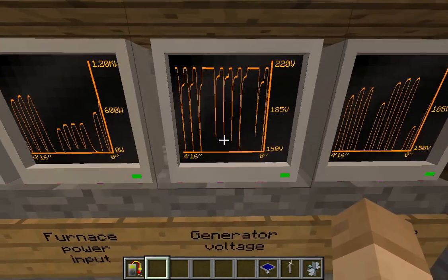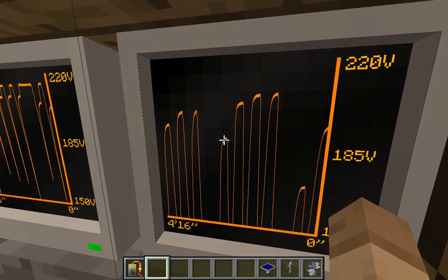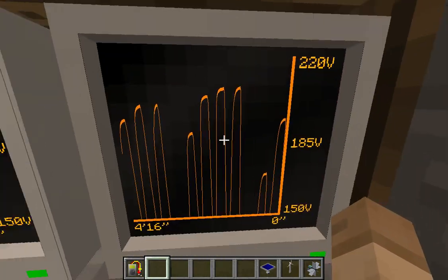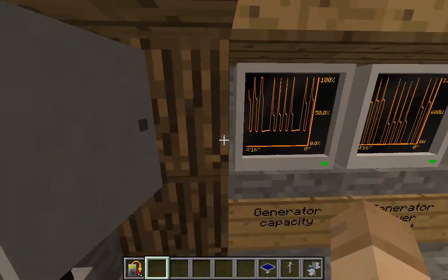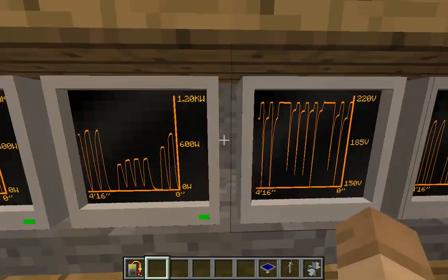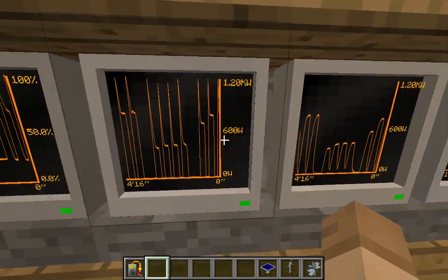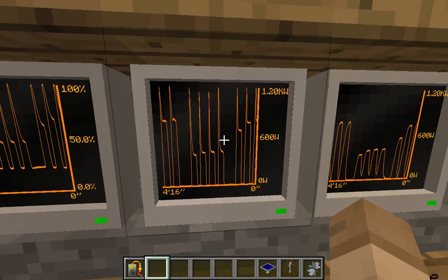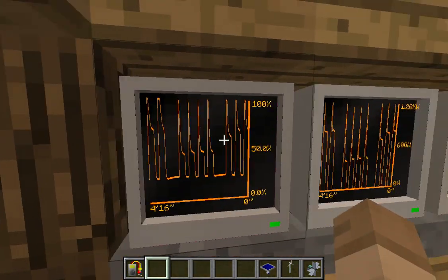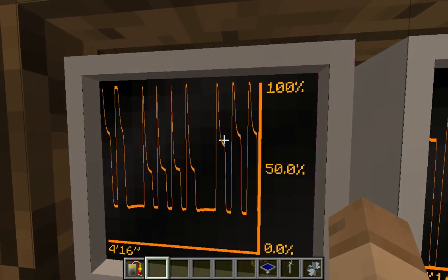It's also obvious that the voltage is going to drop for using the 50-volt cable to transmit the power, simply because there's voltage losses on the cable. So, as we can see, this voltage drop results in less power coming to the furnace, which results in the generator needing to produce less power, which results in the generator running slower. So we can see here for the 800-watt furnace using the 50-volt cable.